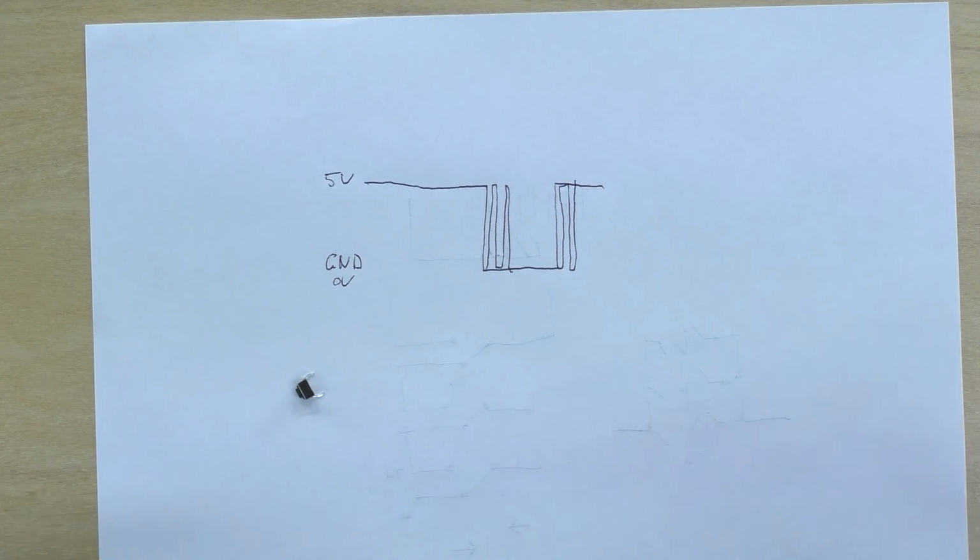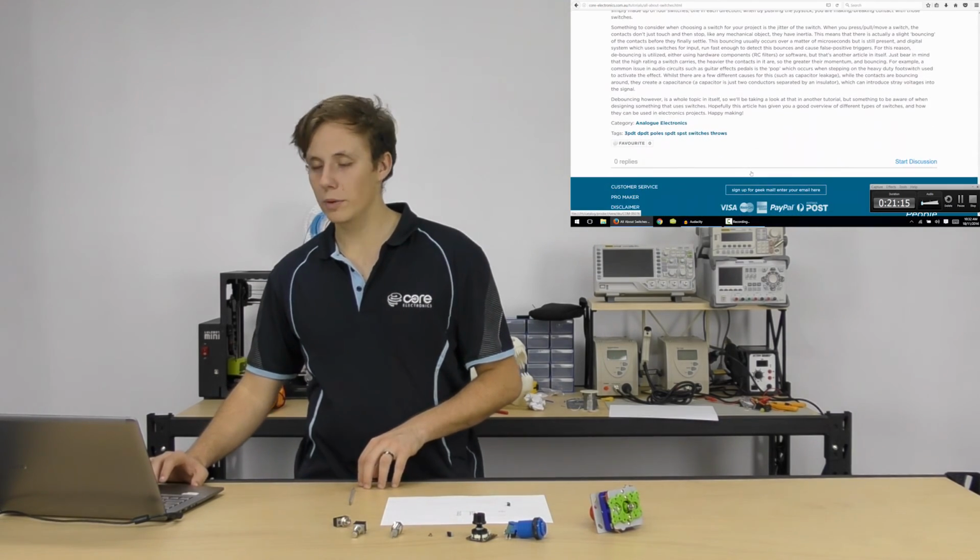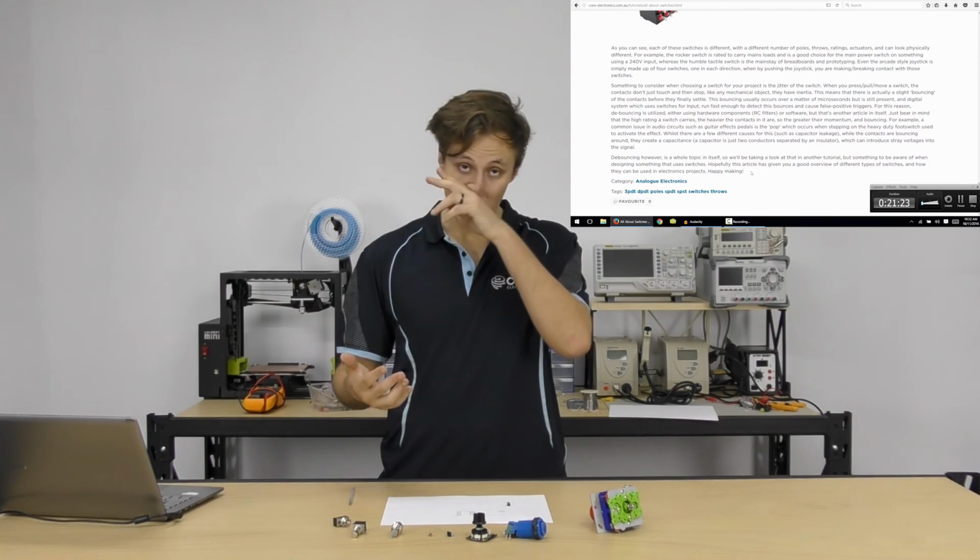So you need to use what's called debouncing. And we're not going to go into debouncing in this video or this tutorial, because it's another conversation in itself. There's a lot of different ways you can do debouncing through hardware: resistor-capacitor filter networks, Schmitt triggers, flyback diodes, and all the rest. Or you can implement it in software by limiting the number of times that button can trigger an action for your microcontroller. So we'll get that tutorial up for you. But pretty much every project or tutorial where there are switches, you're going to find some form of hardware or software debouncing in there, because it's really important.